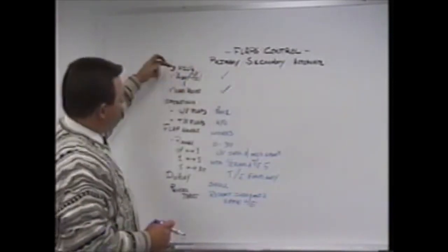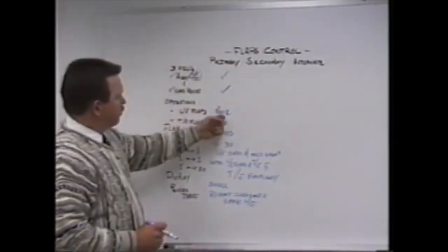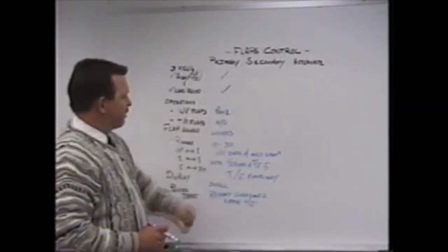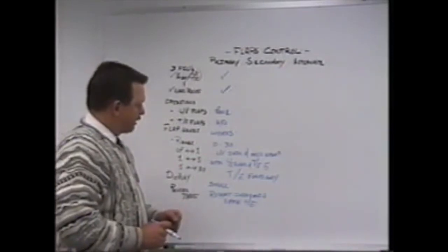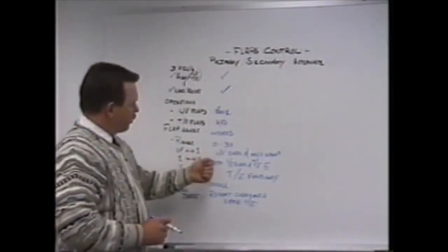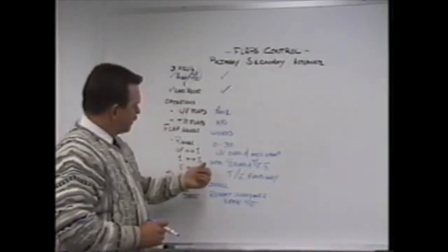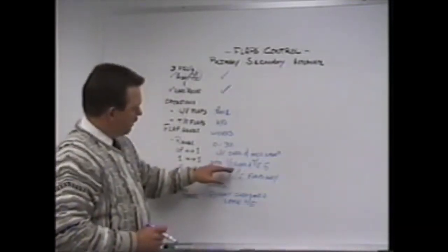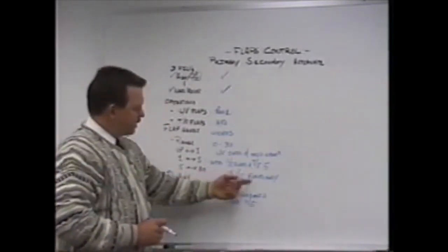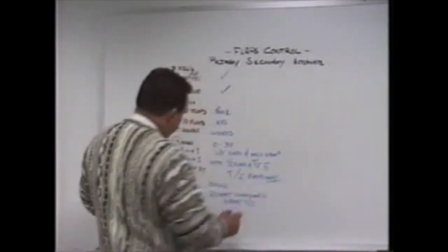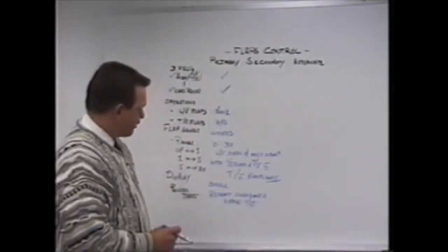And that's a function of the 3 flap control units to provide those 2 protective features. Leading edge flaps are pneumatically operated, trailing edge flaps are hydraulically operated. The flap panel does work. You can select anything from 0 to 30. Flaps up to 1, inboard and midspan leaders only. Flaps 5 to 1 or back either way, outboard leading edge flaps and flaps to 5. Flaps 5 or greater is just trailing edge flaps only. Going into reverse thrust, leading edge, inboard, and midspan will retract.